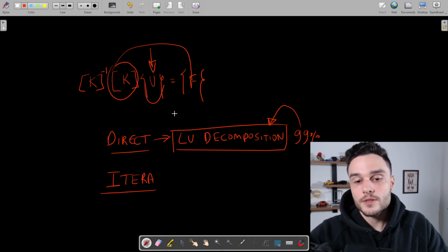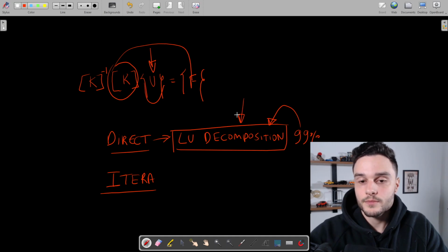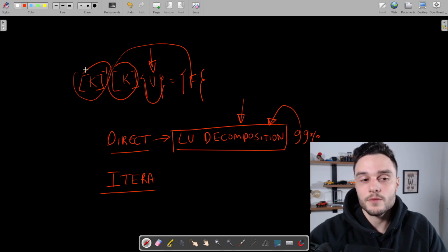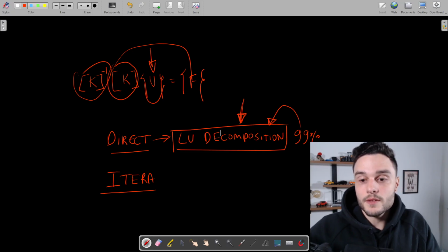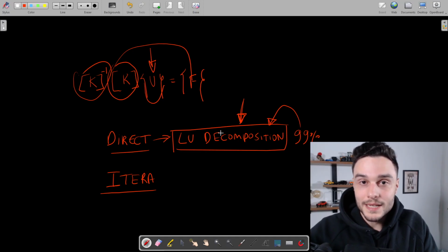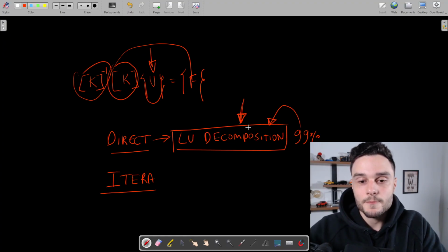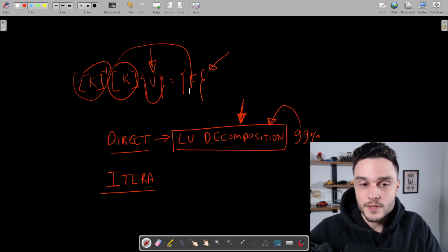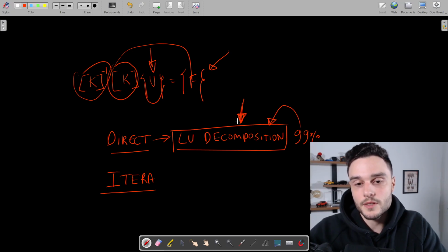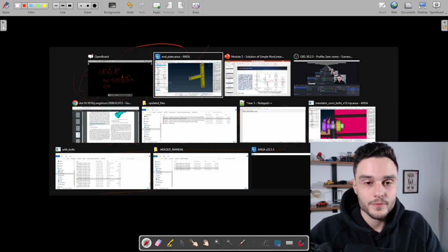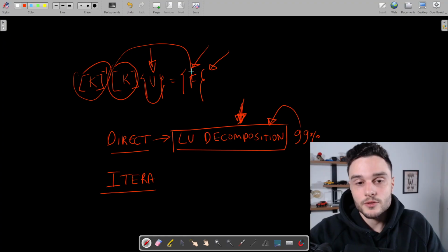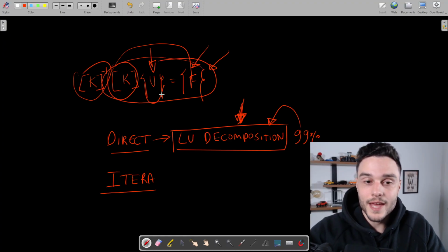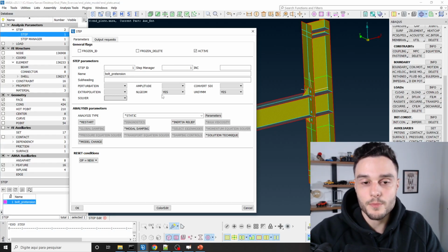Just one last note. Remember that even though this is a numerical procedure that we use instead of inverting the stiffness matrix, the solution is exact. It doesn't mean that it's going to solve the mathematical model exactly. It just means that this method is going to solve this set of algebraic equations exactly. But in this calculation, we know that we have errors introduced because this is a numerical procedure. Okay, but at least this solves this set exactly. But it doesn't mean that the exact solution of this set of equations is going to bring the exact solution of the mathematical model. That's my point.